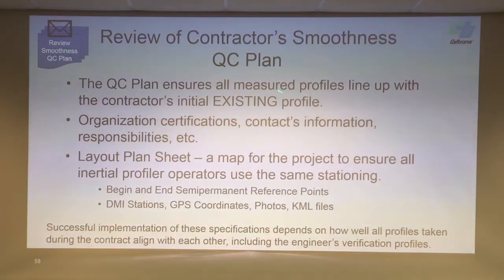Anybody that comes out to that job with a profiler is going to use the same station and the same direction of increase. The organization certs, contact information, responsibilities, that layout plan sheet, that's the plan sheet that's going to have all that information. Anybody that's going to run the inertial profiler will make sure they use the correct plan.